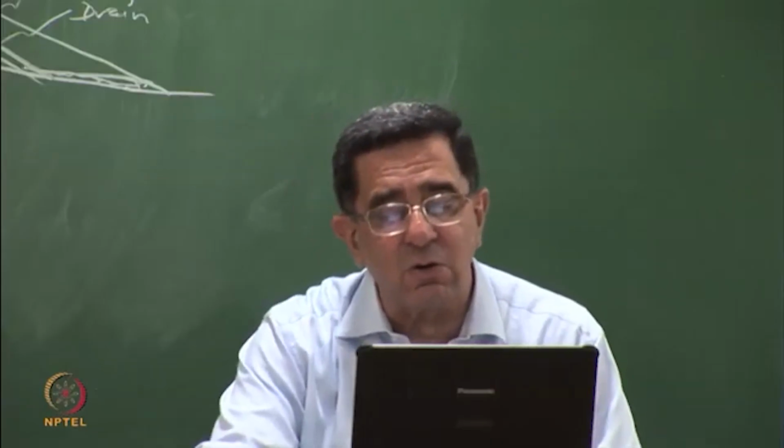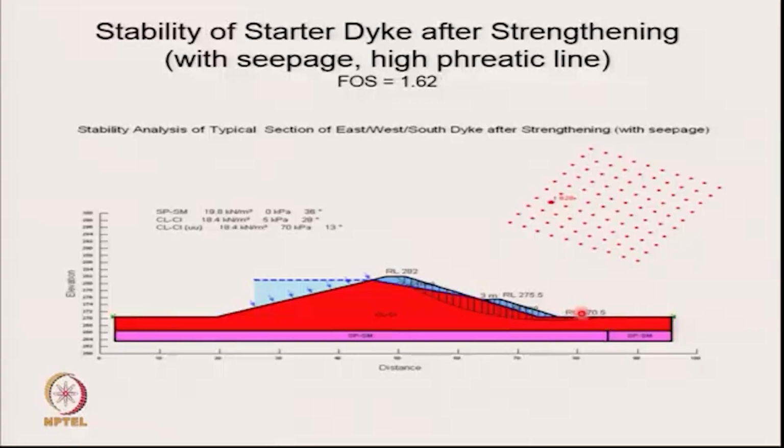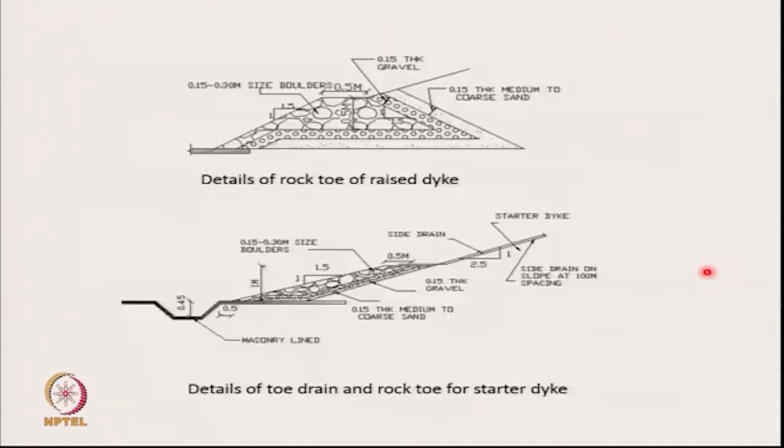I can also do a mid-height berm here. Because once you increase this width, all that will do is increase the resistance on the downstream side. So this is another form of a berm. Here of course, the entire rock fill or boulders or cobbles have been used instead of the local soil, but this is more expensive. However, the width has been reduced.